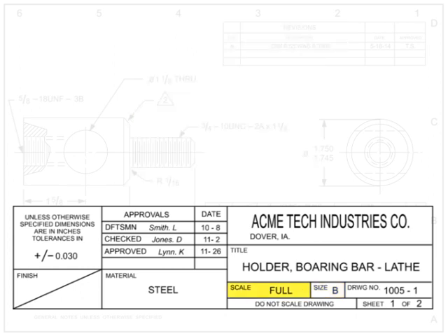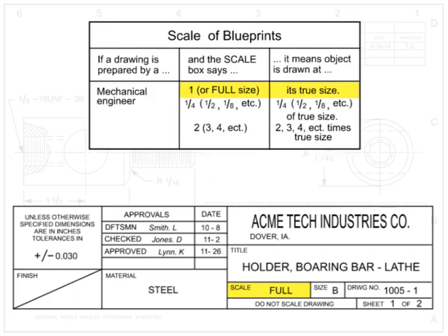The scale block indicates the size and scale of the drawing. Some items, such as large machines or buildings, are simply too large to be drawn life-size or to scale. To ensure the depiction will fit on the drawing, drafters have the choice of either drawing things to scale, larger, or smaller than the actual item. For most drawings generated by engineers, the first number on the scale corresponds to the size on the print. The second number is the size of the part.